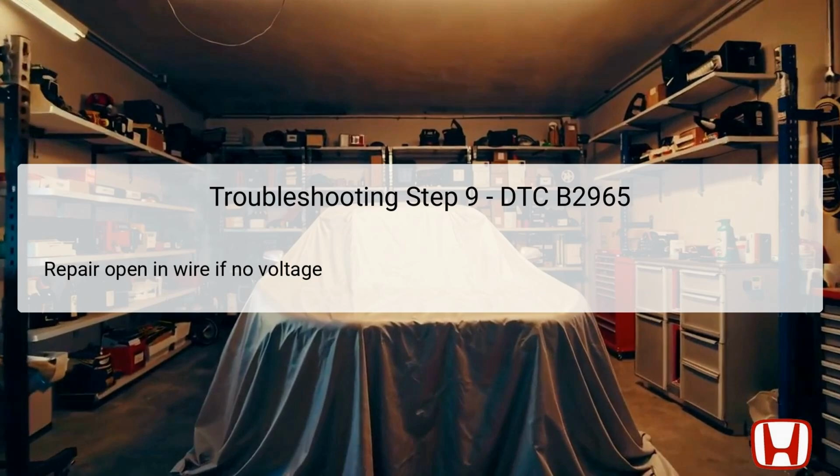A visual inspection can help identify obvious faults such as frayed wires or disconnected components. Once repairs are made, it's important to recheck the voltage levels to ensure the circuit is fully restored, confirming the issue has been effectively addressed before proceeding further.